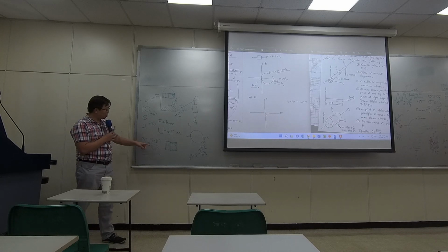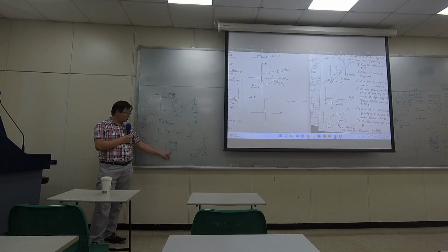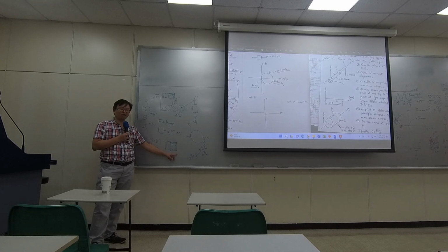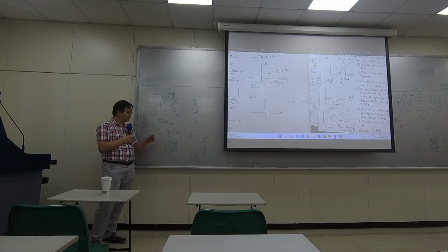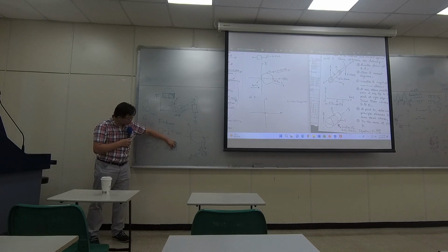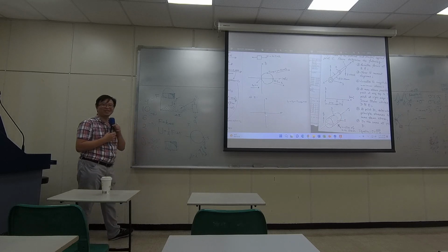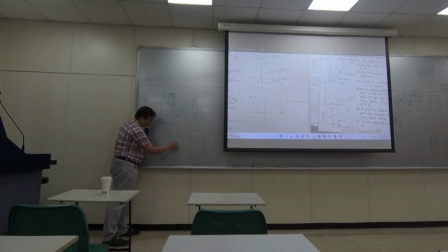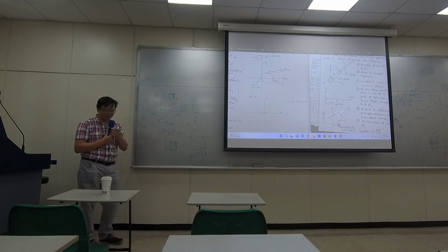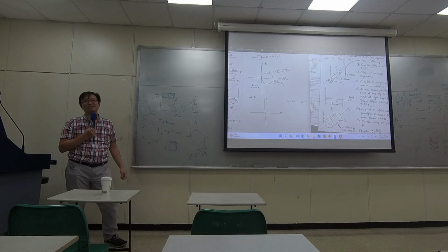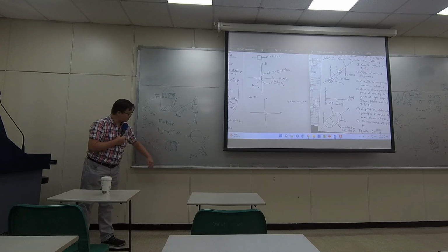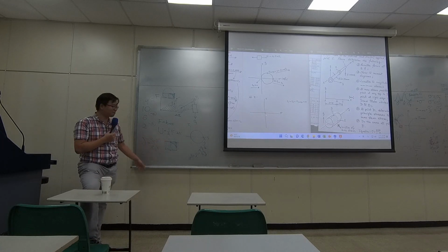But if you truly want to compute this, you need to take integral. It's very troublesome, because it's a distributed load along the cross-section. You need to figure out what would be the shearing profile, and then realize how much shear you have. Then you can figure out what would be the shearing stress right here. It won't be linear. It's non-linear because it's a distributed load.